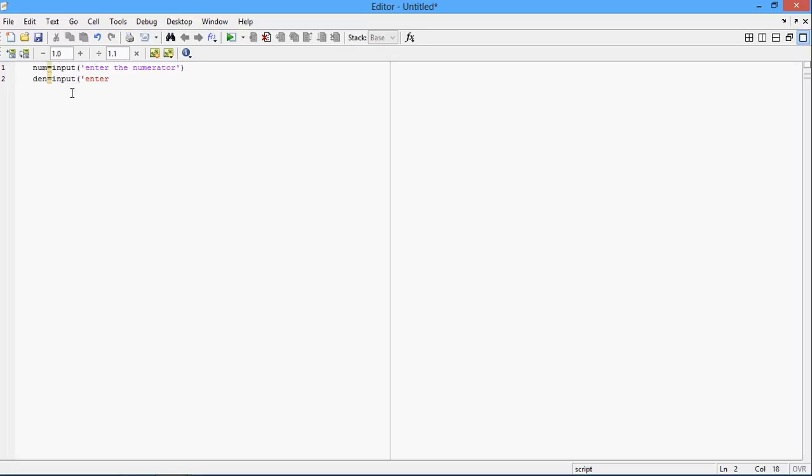And this state model, I tell you, can be different from what you obtain from theoretical calculations, because it all depends on our assumptions. But if you are going to convert this state model into a transfer function again, you'll get the same transfer function. That will be right. So for the given set of A, B, C, if you're taking all of them from the same, then it's going to be right, because based on your assumption, the contents of A, B, and C can differ.